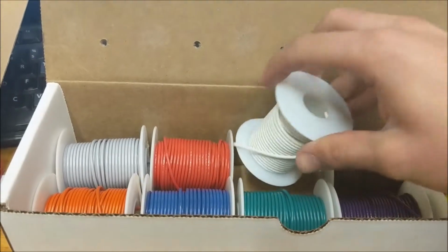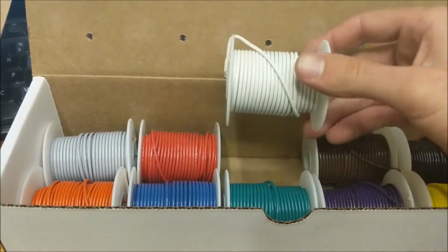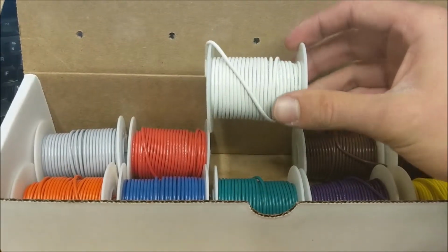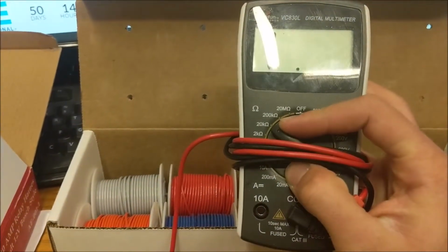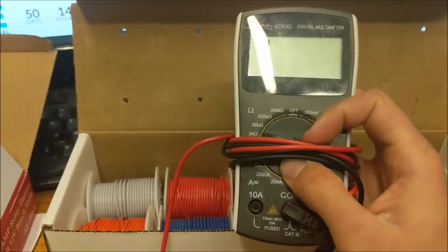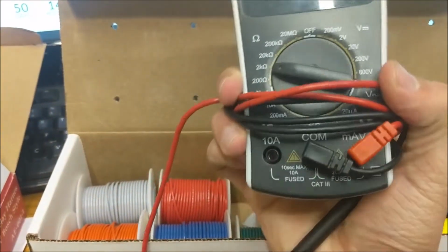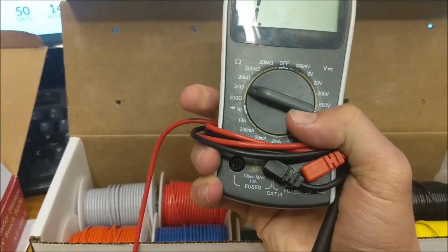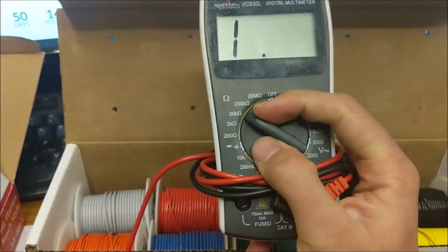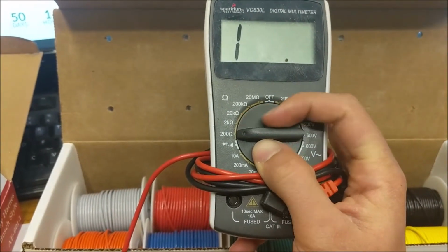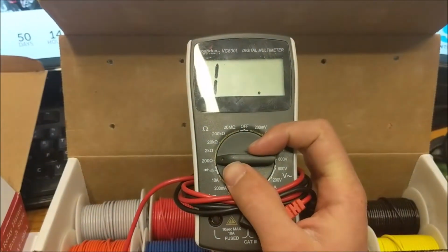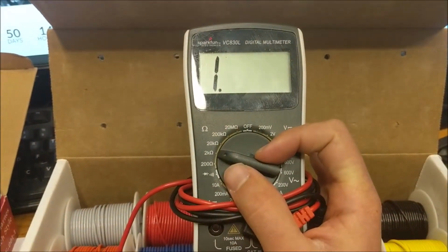Wires can fail in your circuit. This will cause either a break in your circuit or a major short, causing catastrophic failure. Take your multimeter and run the ohm meter through it. Start on a lower ohm setting and then go up from there. If the resistance is too high, your wire may be corroded. If the resistance does not show, or it shows NA or 1, then your wire may be broken.